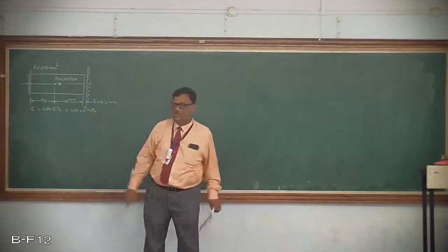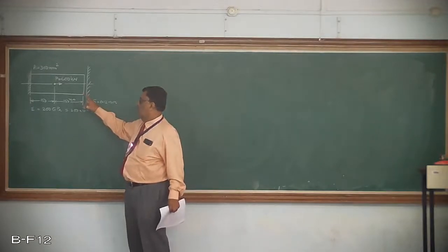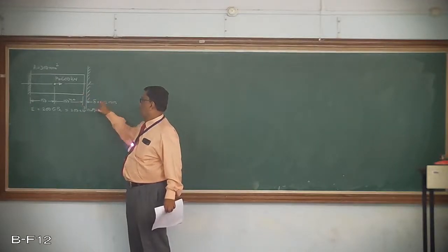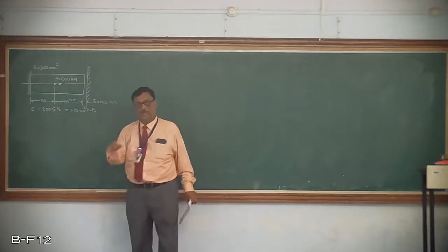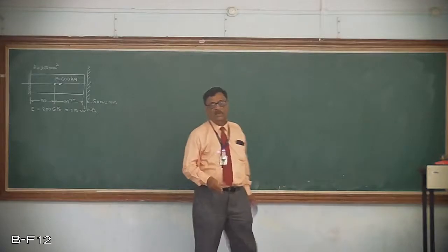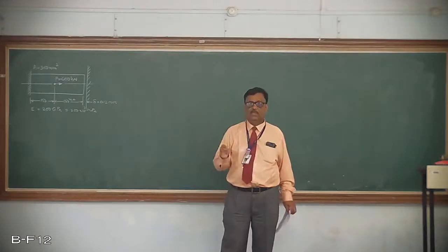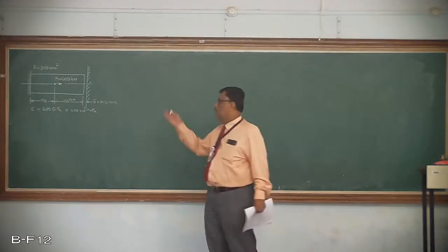So the stresses will start inducing in this member only after it has deformed by about 0.12 mm, and after that, whatever is being prevented will induce different kinds of stresses in these members, either tensile or compressive, depending on this.